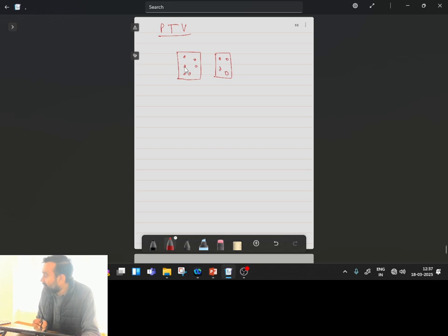I will not make correlation for the entire grid, but I will consider, say, this was my old location of a particle. For this old location, I will create the cross correlation function with all the new particles present in the next frame, and wherever this cross correlation works well, I will consider that my new location of the particle.